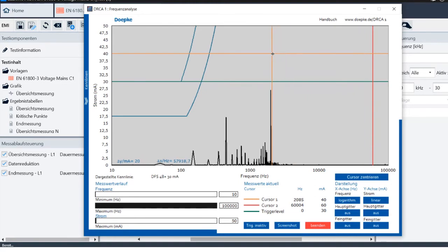And what we also see here is that we have now added leakage current in the lower frequency spectrum. So here we have just as the highest frequency, more or less the 2 kilohertz switching frequency, which we saw before. But we also see additional peaks for the 50 hertz here, for example, or the 150 and 450 as well. So these are the multiples of the 50 hertz grid frequency, which we see now in the leakage current.